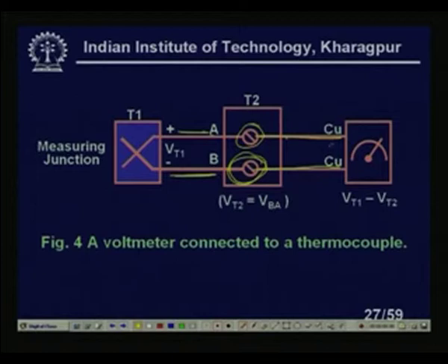The net output voltage is what we are measuring, because we are connecting with different wires. Obviously, if different wires, dissimilar metals, are connected, a thermocouple will again be developed. This can be easily managed if these two are put in an isothermal block. That's what we talked about.